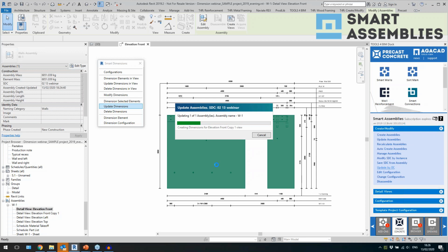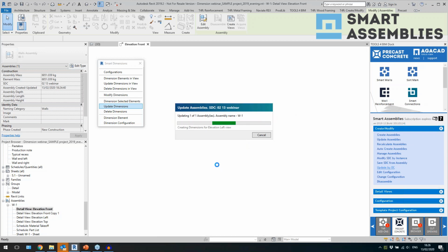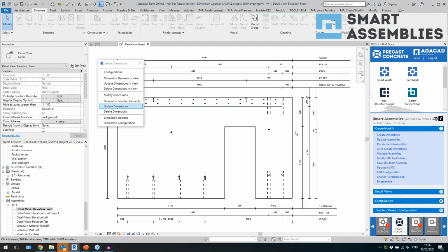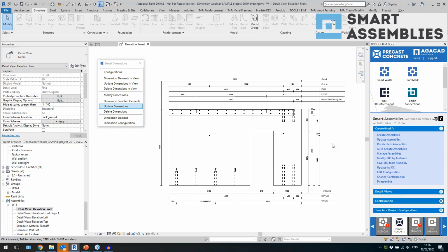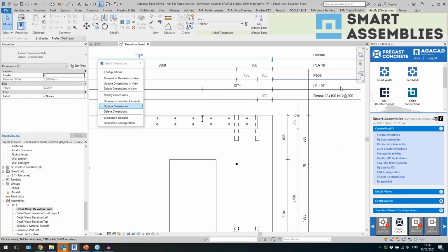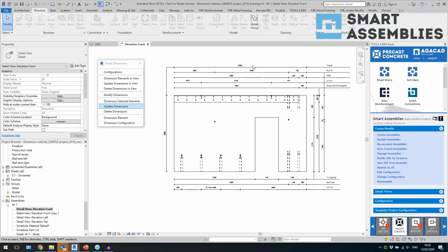So it's just gonna run through all the details, right? It calculates assembly mass again, and note that details are automatically added. You don't need to do that manually. But now I don't have that hole dimension, and I have this total measure with this kind of note. And I have these to the nearest side. These are to the nearest side of this detail. And vertical dimensions are on the right side, except the total measure, which I still left as it was in default configuration. So that's pretty good, and I can get rid of this one.